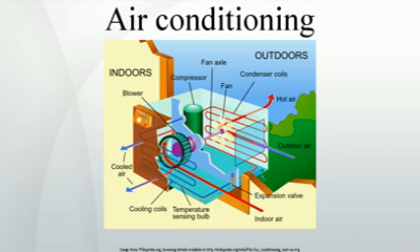Uses. Air conditioning engineers broadly divide air conditioning applications into what they call comfort and process applications. Comfort applications aim to provide a building indoor environment that remains relatively constant despite changes in external weather conditions or in internal heat loads. Air conditioning makes deep-plan buildings feasible, for otherwise they would have to be built narrower or with light wells so that inner spaces received sufficient outdoor air via natural ventilation. Air conditioning also allows buildings to be taller, since wind speed increases significantly with altitude, making natural ventilation impractical for